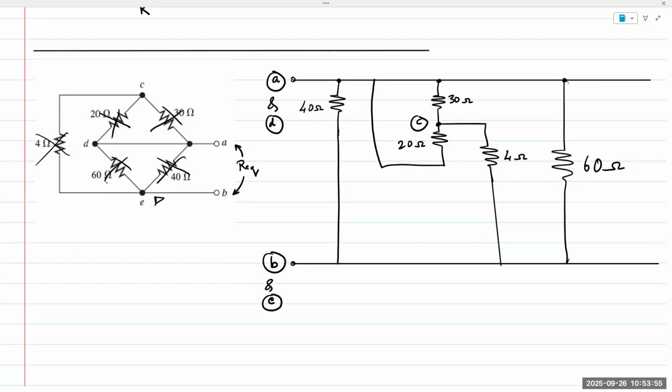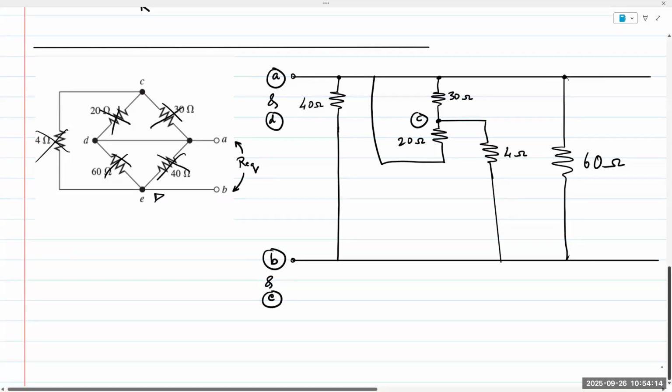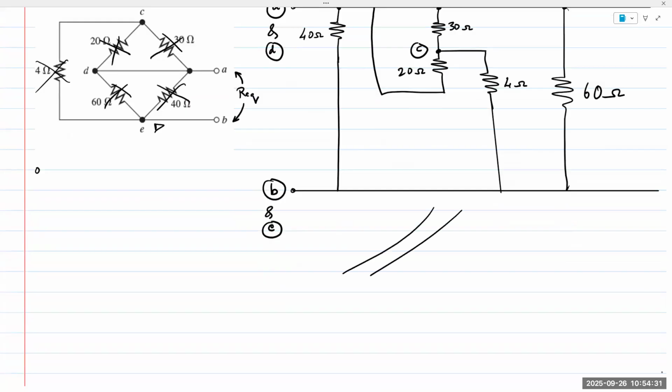Now all resistors are vertical, so I can begin analysis of the circuit. The easiest thing I can see to reduce is the 40 ohm and the 60 ohm resistors. They are both in parallel, right? Since I've solved this before, I know how it goes. But let's say I'm solving this for the first time. This still doesn't quite make sense to me, so I'm going to redraw the circuit again. This time I know how much space I need. Actually, let me just draw it right below.